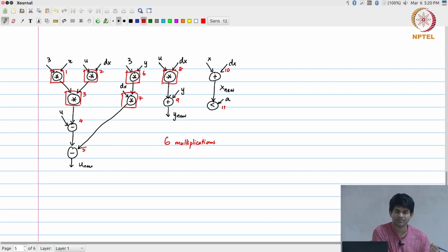Rather than saying I need separate hardware units for all of those, addition and subtraction at least we know can be done by the same hardware, because you just use 2's complement and addition and subtraction essentially become the same thing. Comparison is also essentially the same thing, because all that it involves is you do a subtraction and check whether the result was negative or positive. So, what we have is 5 operations that I am going to call ALU operations. A total of 11 tasks need to be scheduled, and what we are going to look at is how I go about this systematically, and whether there are any ways by which I can systematically solve this particular problem.